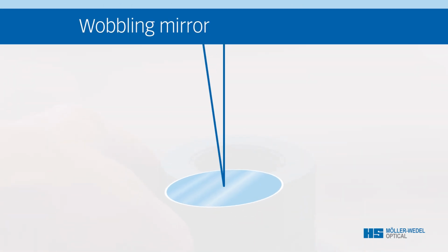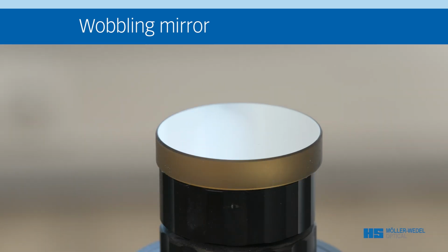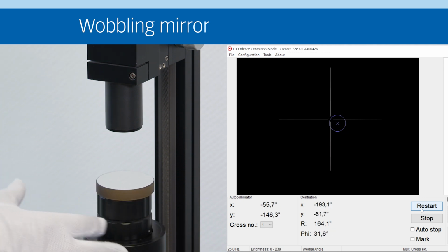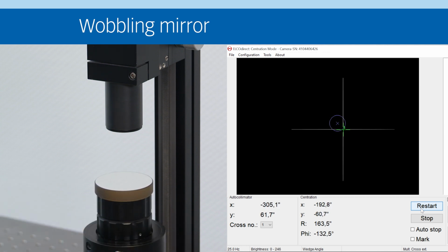Wobbling mirror. In centration mode, the wobble of a reflective surface is shown in this example. To do this, the mirror is rotated in front of the autocollimator. The Elcomat Direct-N continuously measures the angle of the rotating surface. After a complete rotation, the ElcoDirect software displays the exact amount of surface wobble and its orientation as the angle phi.